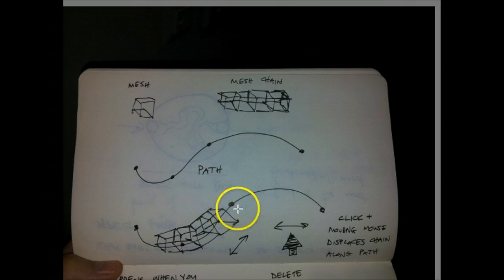We could also change the rotation at a fixed point in space. So imagine if this mesh point here, we said we want the rotation to be a certain amount at this point, right? Then if we push this mesh chain along, it will stay flat, and as it starts passing this point, all these mesh links will start to rotate. And if you keep pushing it, it'll be like a wave of rotation goes through this mesh chain, because we're saying anything that passes this point must have a certain rotation. So can you see what I'm trying to get at?